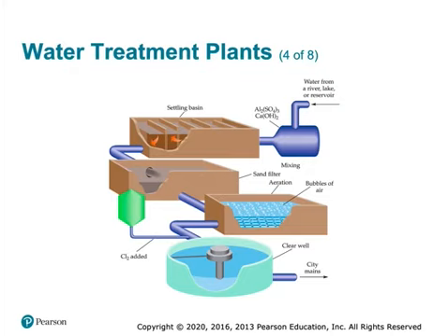Typically, you have anthracite coal in this as well. The anthracite coal makes a sand filter last a long time. And you can clean the sand filter by reversing the flow of the water. When you reverse the flow of the water, you get rid of all the gunk. And so you can do that a few times before you have to replace everything in the sand filter.